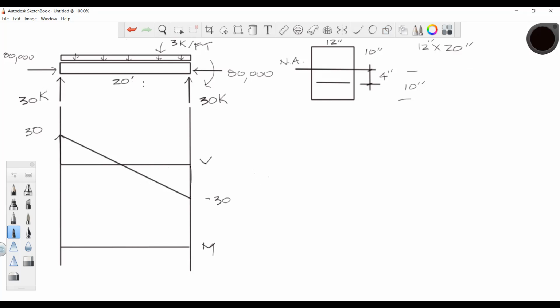All right, so we have a 0 line that has our 0 point of shear. Where is that 0 point of shear occurring? At the middle. Right at the middle. Yeah, so we know that that's 10 over. That's correct. So this is 10 and that's 10. So we have a maximum moment that occurs there, right?